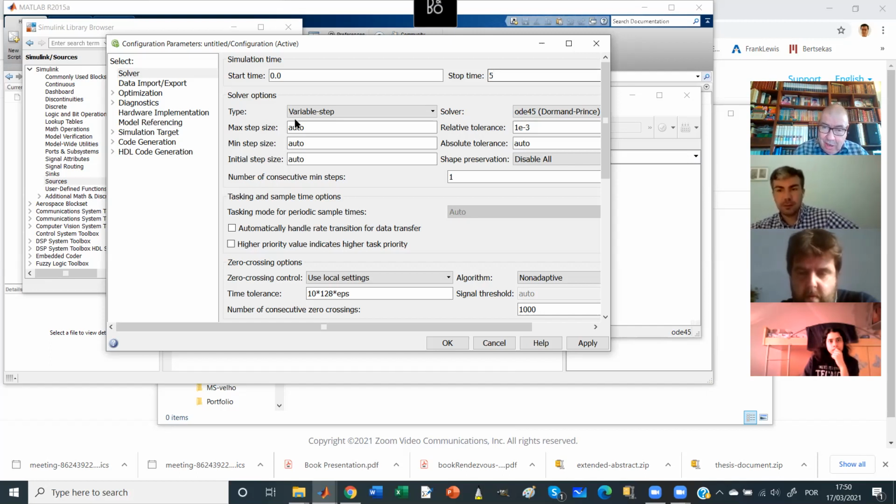And then there's another thing, which is to compute just once with 2 seconds of step time and compares both solutions. If the difference between them is smaller than this relative tolerance, then divided by one of them, then you go on increasing the step size. Otherwise, you decrease it until you are at a limit in which they are both good. Okay, that's the way they work.